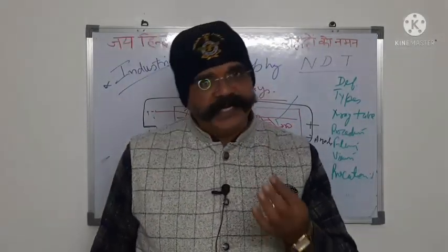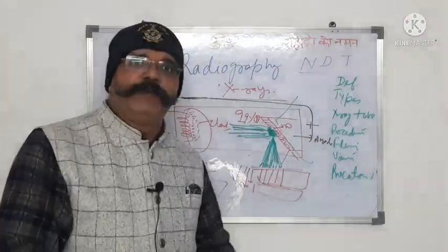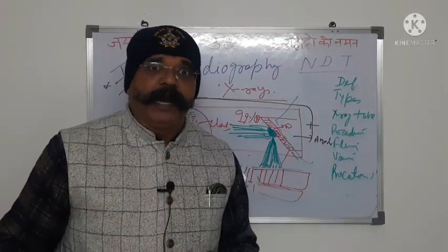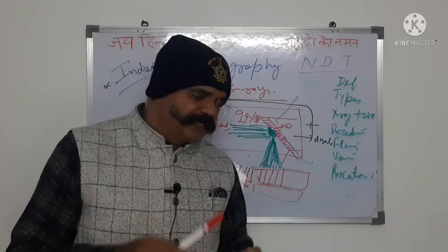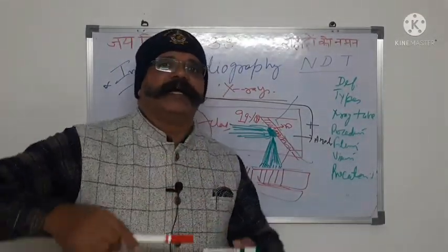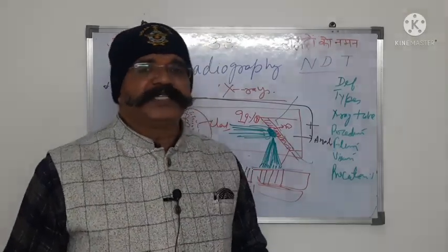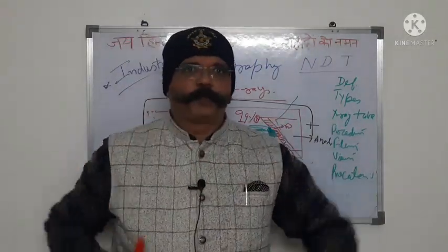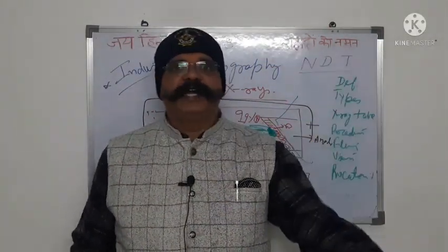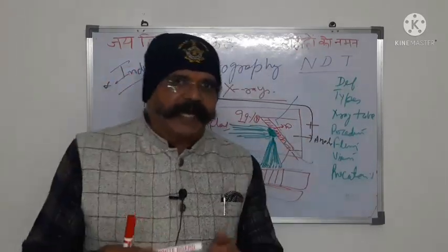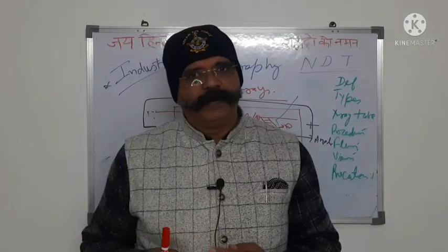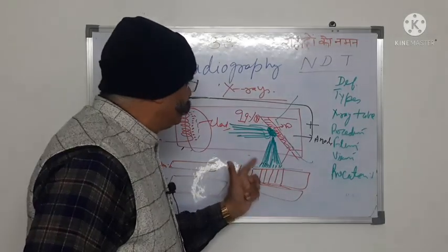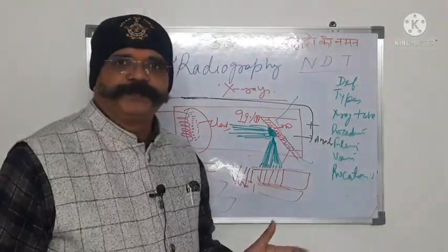This 2 mm sheet is very thin, so the high energy X-ray will penetrate approximately all portions of the material, and even if it crosses the cracks, it will cross the other portion also. But since the energy is very high, the whole film will be darkened in such a proportion that you may not be able to differentiate, while viewing the X-ray film, where the crack is and where the normal plane is. So these energies have a very significant role in X-ray radiography.